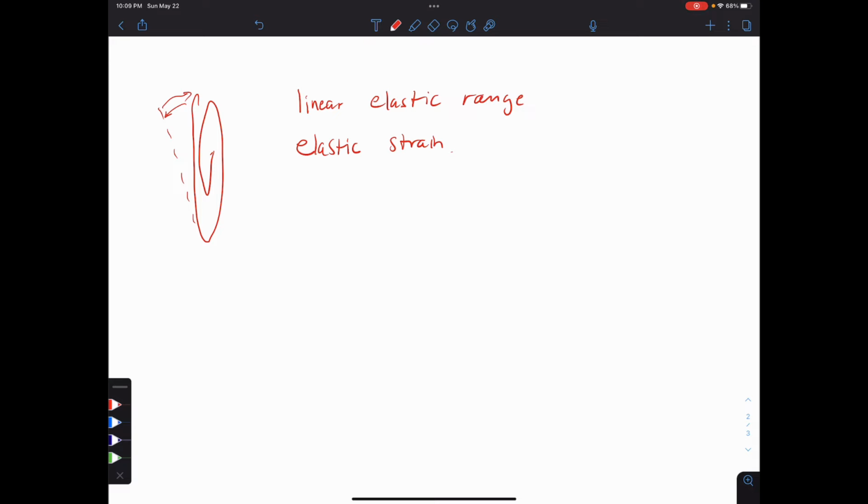If I move to pushing this further, I bend it over, and now I let it go, and it got all the way to here, let's say, but when I let it back over, it only springs back to this point here. Now I have a combination of, in here is the elastic portion, and then up here is a plastic strain region. I have permanently moved the material.